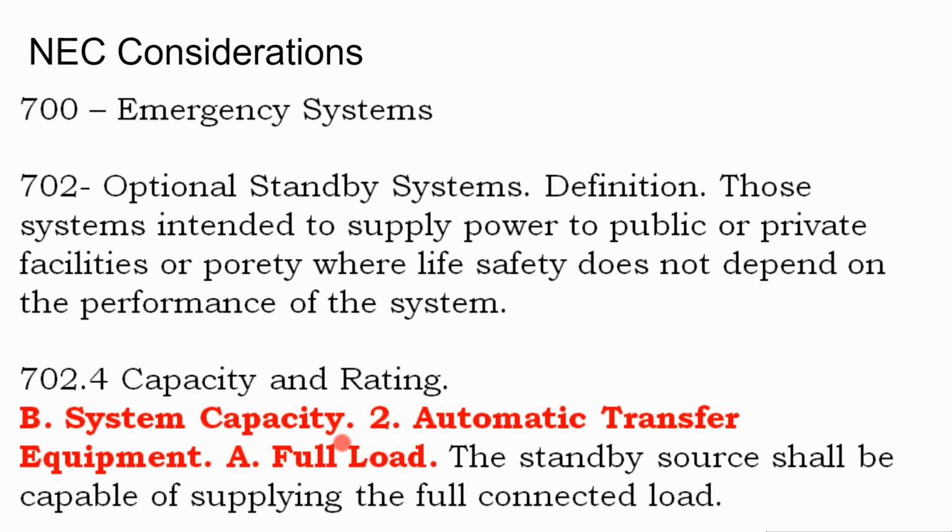And so that's where the solar battery grid tied companies will say we're only going to output 2 kilowatts of power on a critical load. They're not capable of supplying your whole house. Even if you had a 6 kilowatt battery inverter, that's generally not enough to supply a whole house.